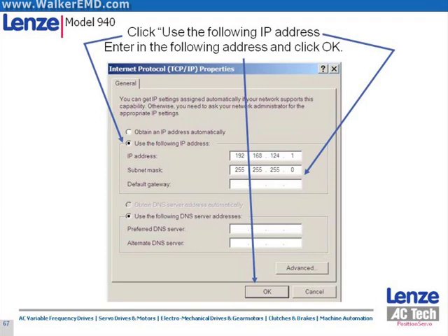The default value of position servo's last octet of its IP address is 120, so any address other than 120 will work if the only two devices on the network are the PC and the drive. For example, you could set it to 1. Enter 255.255.255.0 for the subnet mask, and then click OK.